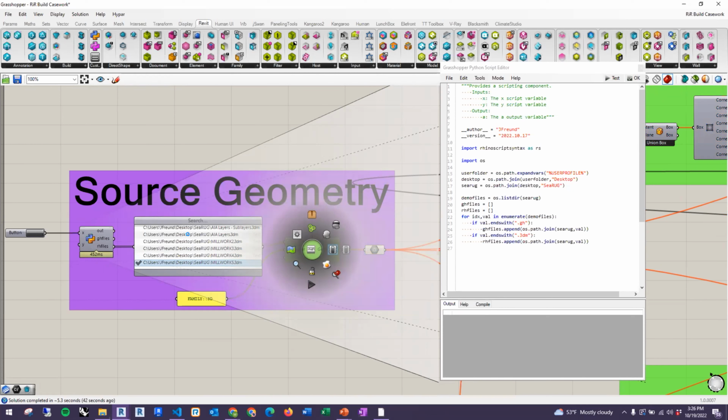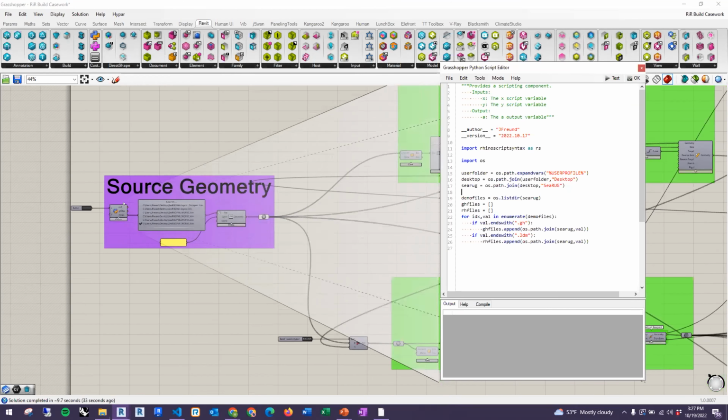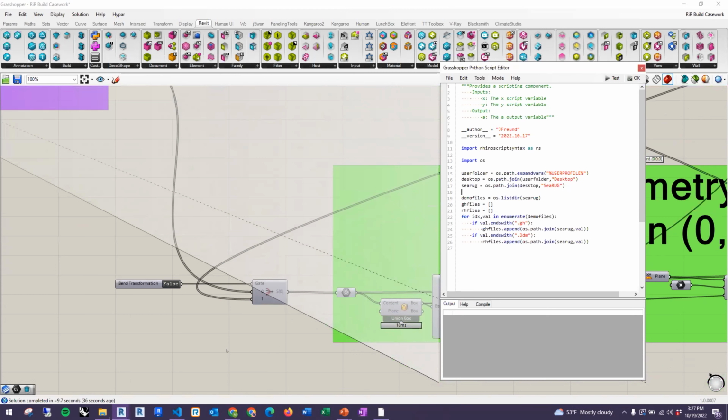While that process runs, I'll note that this is one of those areas I mentioned where, if you have a standardized way that you've modeled all of your Rhino geometry, you can place it on layers and sublayers that allow you to automate these processes. So when you have the Grasshopper definition look to a particular place within the Rhino model, it's going to be able to find all of that information that it needs there, including even the name of the object.